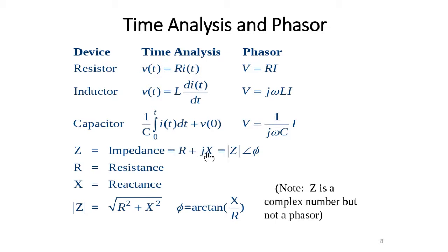So the X is not only the reactance here. It could be capacitive reactance. It's not just an inductor here. This could be inductive reactance or capacitive reactance. So it's just this plus or minus. Positive or negative here. So if it's negative, it means this is a capacitive impedance. Capacitive impedance we have, or inductive impedance. And this way here, plus jX, so it is an inductive impedance.